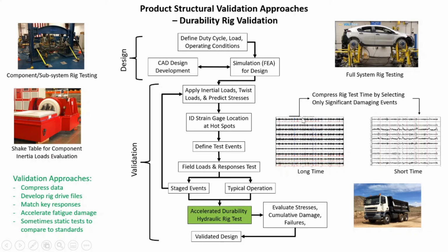So once all this is done, we will do some further processing on this data to essentially develop rig drive files. And these will be the files that will actually drive the hydraulic actuators that apply the loads to the structure. And a part of that process is to match key responses of the vehicle.